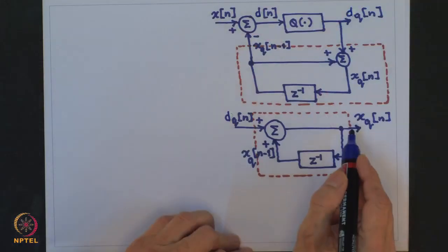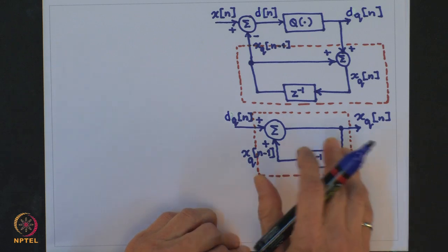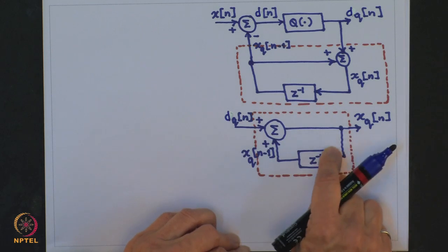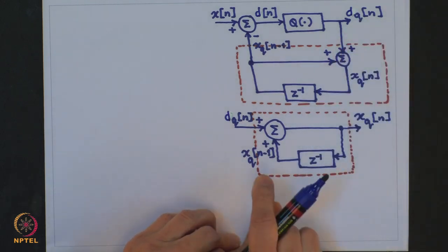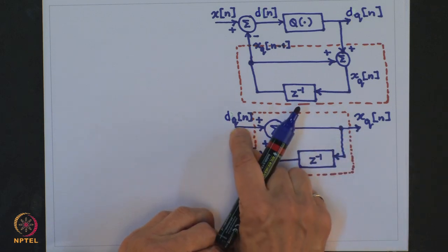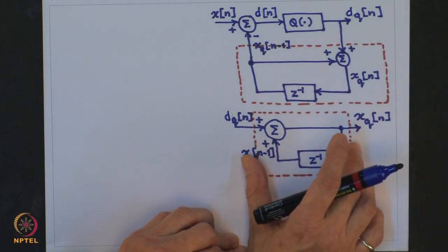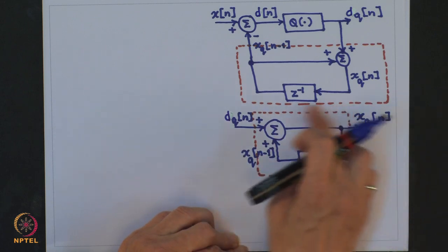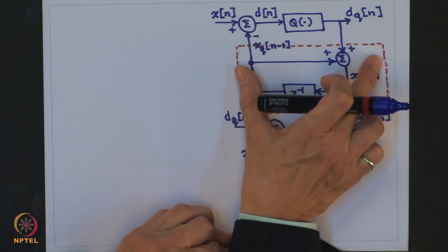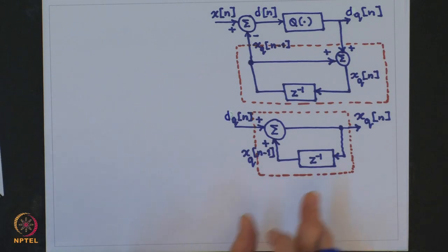So, I have at the receiver this block. Now, what I am saying is that since this reconstruction can also be done at the transmitting end, because it is using for reconstruction at the receiver end only the difference sequence, which is also available at the transmitting end, this block, this red block which I have marked in dotted, can be put at the transmitting end itself. Now if we do this, let us see what we are going to get.